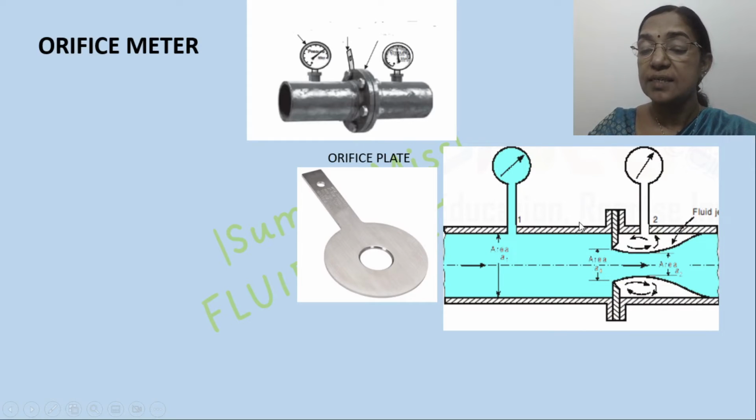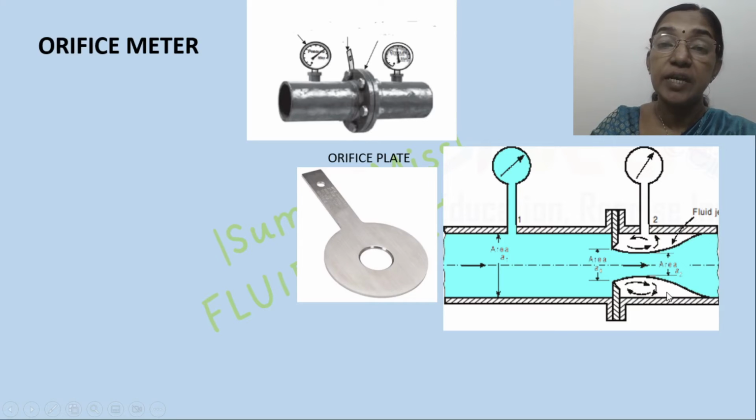The approaching flow gets accelerated towards this orifice and then expands further as the flow area increases. During the deceleration of the flow, there is a separation of the flow from the boundaries. A large amount of eddies will be there in the separated area, which will induce large amount of losses. Because of this flow separation, the flow area also gets reduced compared to the orifice area.